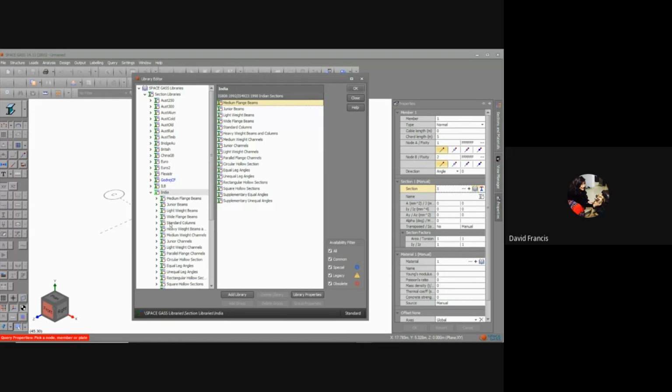I'm a young engineer. I've just joined the organization, and I've been given the criteria of this workshop. Number 1 is we're trying to minimize the amount of steel that we're going to use to achieve the utility we're after. And secondly, deflection, maximum 20 millimeters at any position across the structure. Total deflection, no more than 20 millimeters.